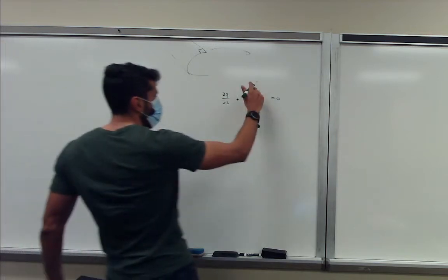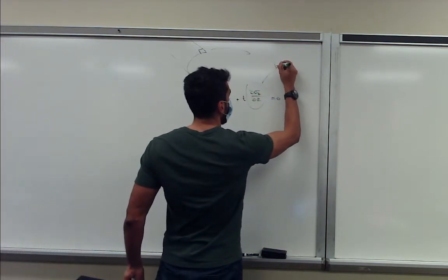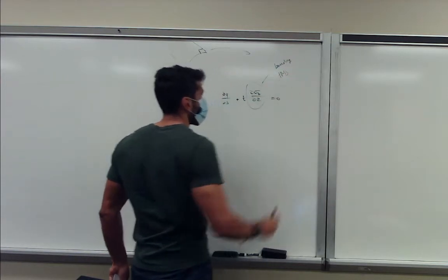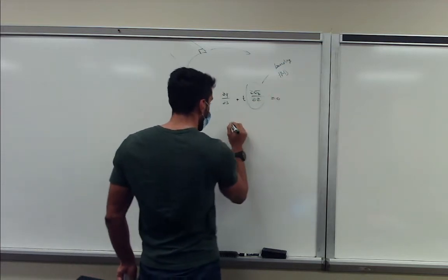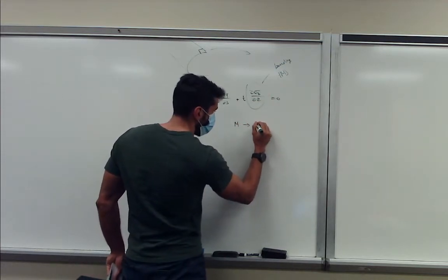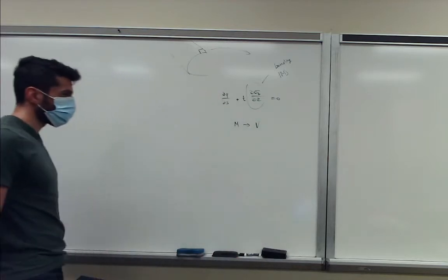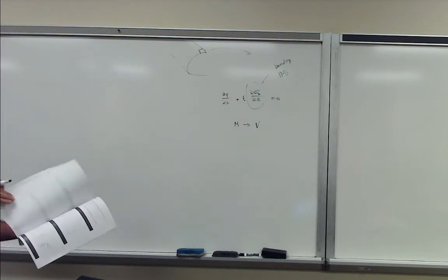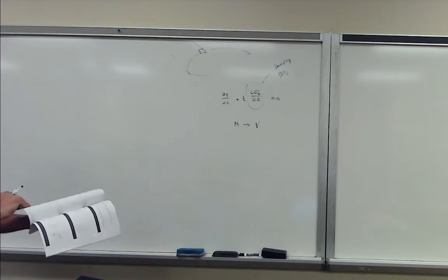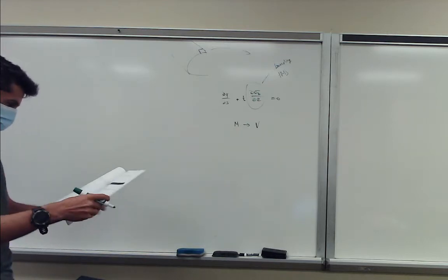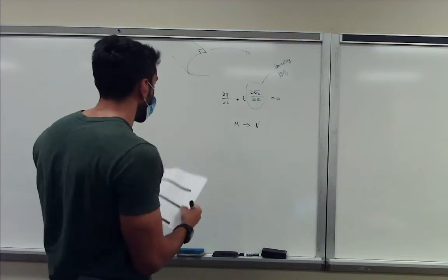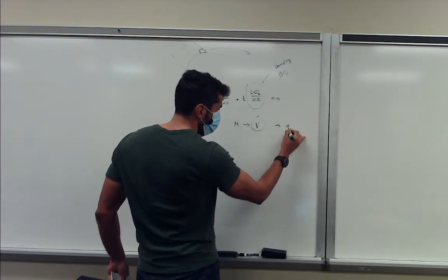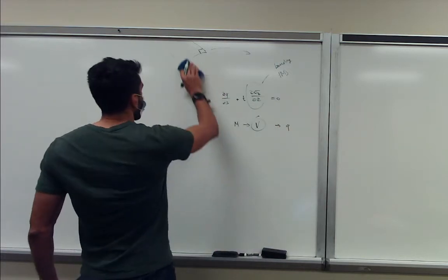And this we already basically identified in bending. So we knew that this is a function of the moments. And what we did is we related the moments to the shear forces. I'm going to call those V for now. And then we plug this relationship back into this one. And when doing that, we basically obtain our equation that relates the shear force V to our shear flow Q. And that relationship looks as follows.